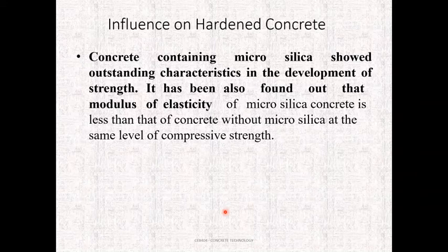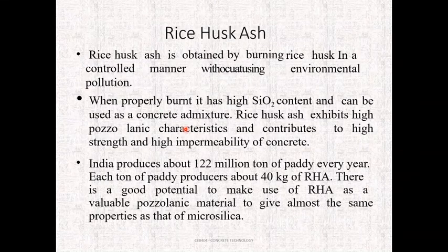The influence on hardened concrete: concrete containing microsilica shows outstanding strength development. It is found that the modulus of elasticity of silica fume concrete is less than that of concrete without silica fume.